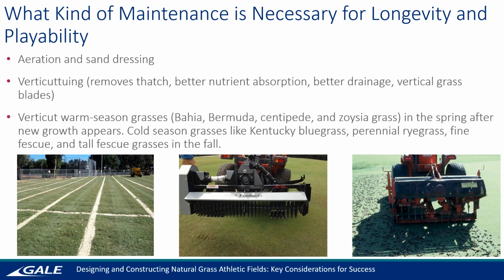So using a deep tine and a hollow tine, where you see these things on the bottom right, they're going in 6 to 8 inches, and they're removing whole plugs of that soil media, and then you come back and top dress it with sand, and you're creating avenues there to decompact it and to improve the drainage and the growth quality of the site.